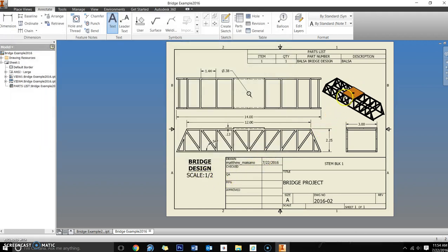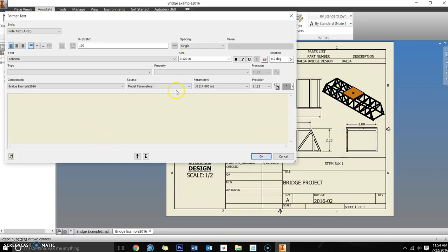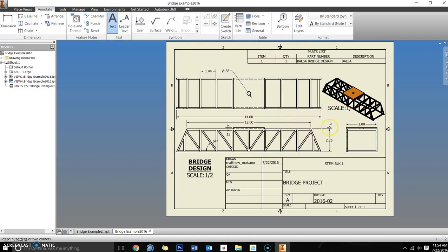We're going to put just a second text box right below the isometric drawing. And again, we're going to make this 0.2. No bold, no underline. We're going to center it though. And I just want you again to put scale. And this one was 1/4. And I'm going to press escape, get my selection cursor. Just move that in a more ideal location. I'm going to bump this up a little bit as well.